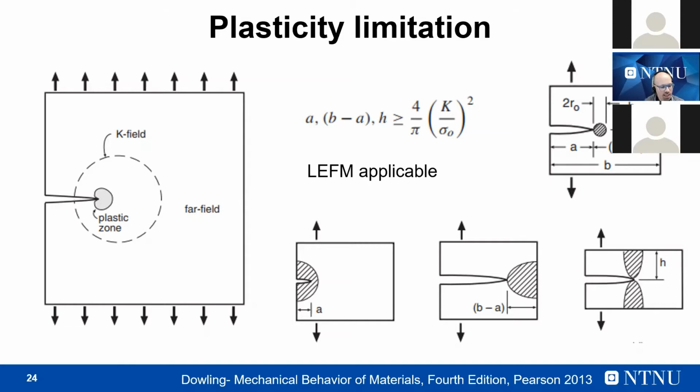So what we would like to do is to have approaches that are easy to use in engineering applications, and to maintain this simplicity, we need to be inside the linear elastic field. Another advantage to be inside the linear elastic field is that we can use the superposition principle, which is another important aspect that under plastic deformation is impossible to do. So, I mean, we need to be careful of these aspects.